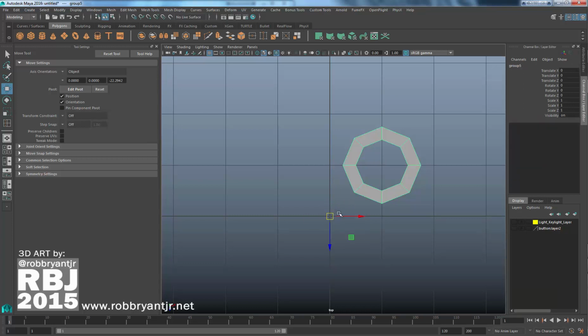at the 0, 0 space, if you click off of it and click on it again, and you notice that your pivot snaps back into its original position, simply press the up arrow on your keyboard and it selects the group mode, which, since we've adjusted our pivot point for the group mode, takes it back to the 0, 0 world space. Just in case you do that and you don't know why your pivot point moved and you want to get it back to the center of the space. Awesome.